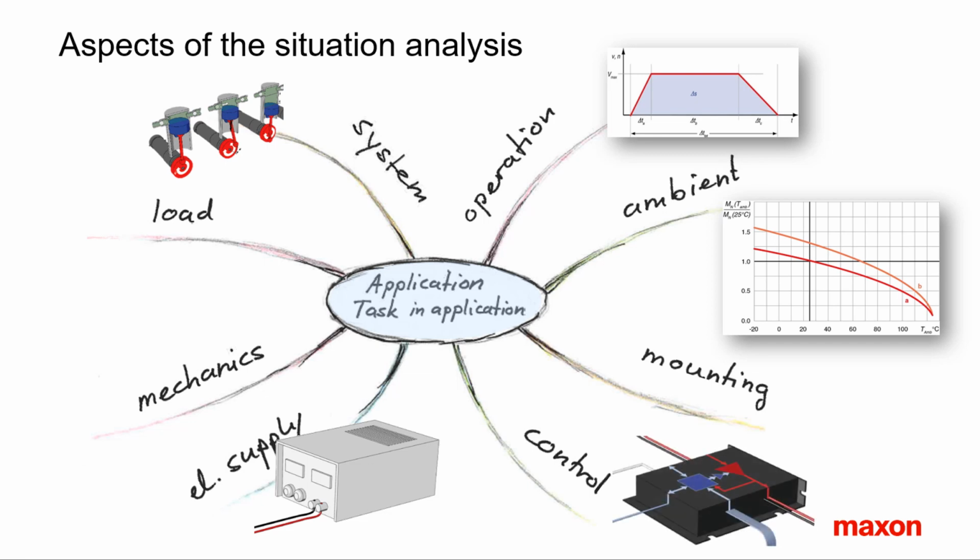Fourth, control concept. Very important. Where do the set values commands come from? What to control? Position, speed or torque? Fifth, mounting conditions, which are also related to ambient, for example, cooling, but also cable length, fixation of the drive.